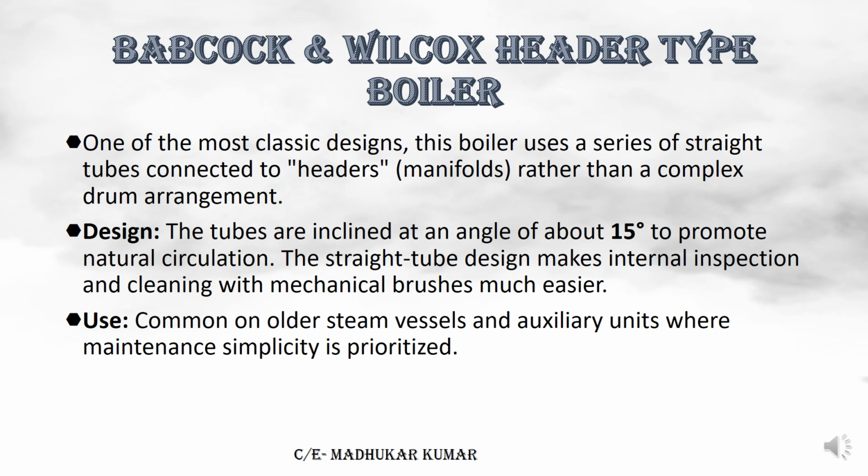It is something which is your Babcock and Wilcox header type boiler. This is one of the oldest boilers used in the marine sector. A series of straight tubes and headers, rather than the complex drum arrangements. Drum arrangements you will see on the fire tube boiler. Here you have the headers and the tubes attached. They are inclined at about 15 degrees, a 15-degree inclination angle, basically to promote natural circulation. So when the water is getting heated up, it is going to circulate, giving better heat transfer.